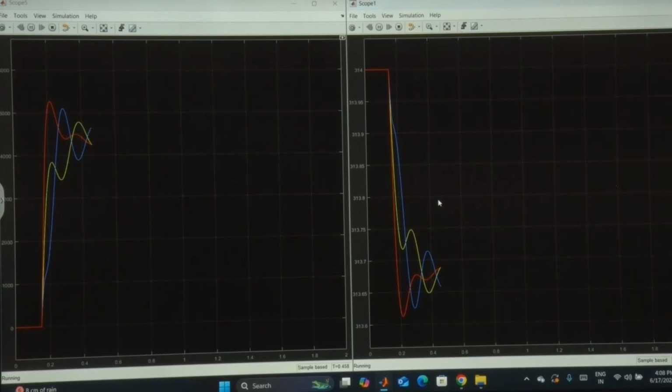All right. And then there is one more thing. If you remember today's lecture in the morning, I talked about the control system stability. In the control system stability, I told that the power controllers introduce low frequency oscillations. As you make it steeper, you increase them. Do you see some oscillations? These are called low frequency oscillations. You have observed these oscillations only because of your controller gains.